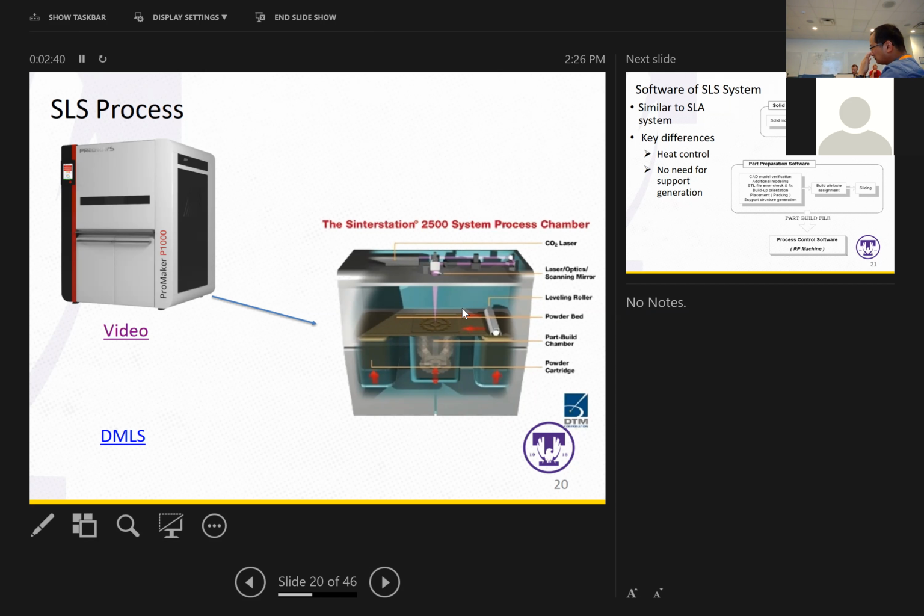Sure, I understand for rapid prototype, but I'm not saying it does not look full blown like a production-ready unit, like they keep telling me. Oh, no, it's not. Yeah, there's a lot of things, and companies are coming out with improvements to the machines, like the Concept Laser X-Line machine, which is a gigantic powder bed metal machine. It's got 2 chambers, so to deal with the powder, harvesting your part out of the powder, the thing just rotates, and so you get a new build, you can start printing on the next print while you're over there digging your part out.